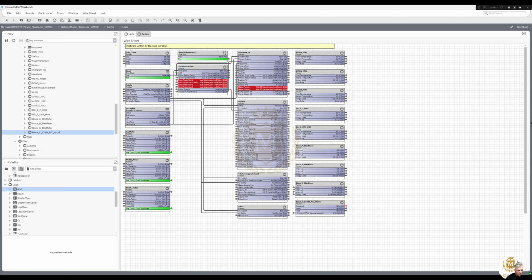So we're occupied. Occupied. We're occupied. Frost protection, valves and pumps enable. Frost protection. So that should be 100%, but I've got no control variable. Safety. Air safety. No, it's pressure. So it's that one. It's water pressure. Right, so there's everything marked up apart from my control variable for block C LTHW pick valve.